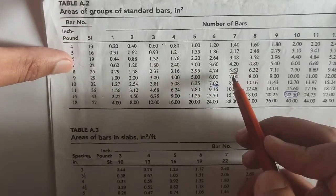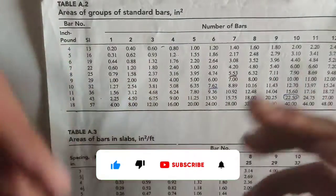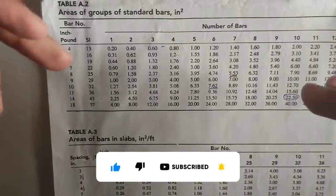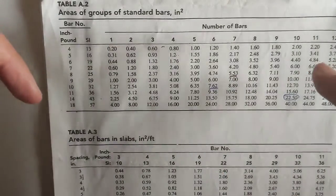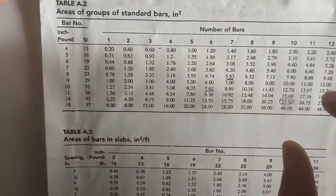You can round off, because 7 is an odd number. You can go towards 8 or towards 6 depending upon your calculations and depending upon your safety factor. So that is the simple way of using the areas table to get the exact value of your bar number.